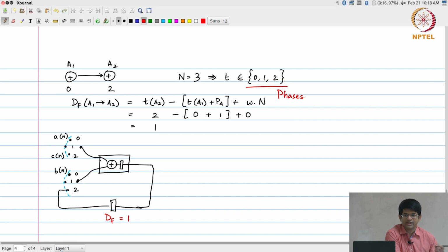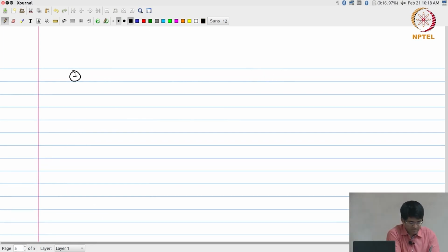All that it tells us is we can automate this process of figuring out how many registers to put when we are taking a particular output and connecting it to the appropriate input. Just to round this off, we will take one further example before going on to a more complex example, which will be useful finally. I am going to take the same a1, a2, but now I am going to say I am pipelining this, put a delay element on it. So this basically says that w is equal to 1.